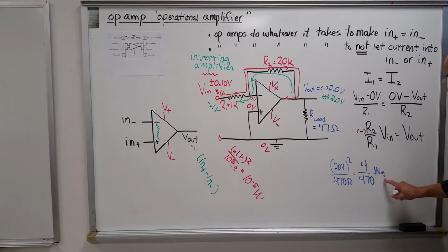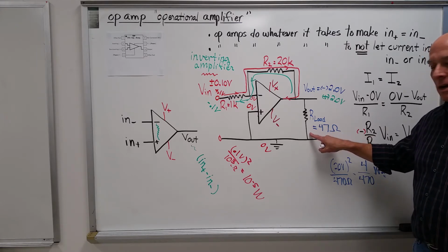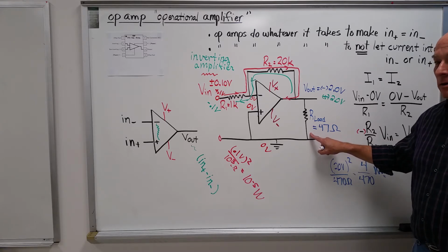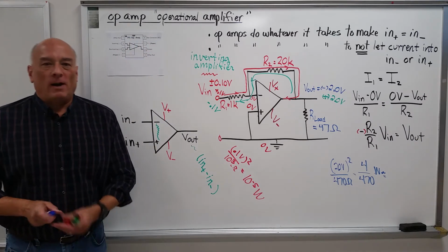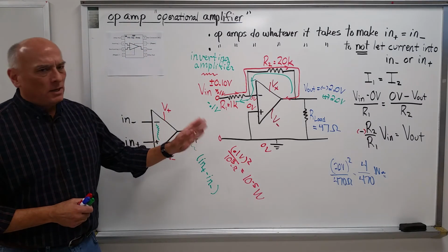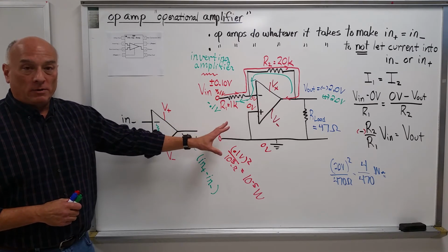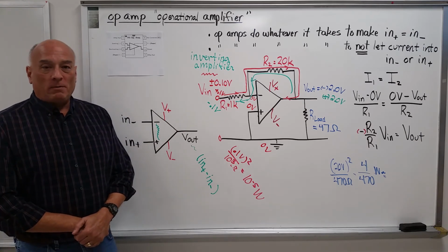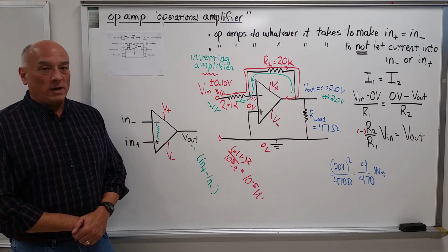So by the time you punch this up, you have also amplified the current, because this voltage has to be maintained across a smaller resistor, but the op-amp will do whatever it takes by putting out whatever current is required to make this happen. So this basic inverting amplifier allows you to amplify the voltage. The negative sign will come into play, but it amplifies not only the voltage, but also the current. The previous one, the voltage follower, simply amplified the current. So these operational amplifiers can do all sorts of great and glorious things.